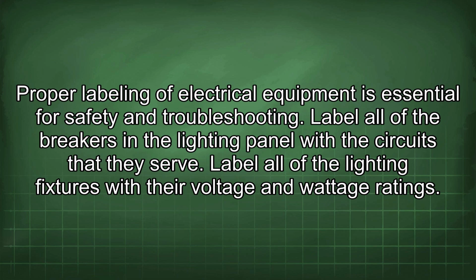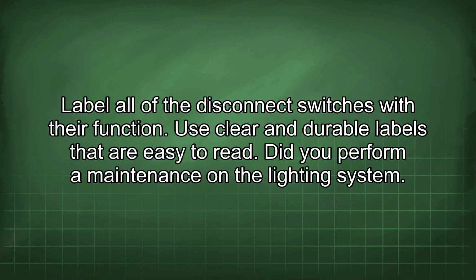Label all of the lighting fixtures with their voltage and wattage ratings. Label all of the disconnect switches with their function. Use clear and durable labels that are easy to read. Did you perform a maintenance on the lighting system?